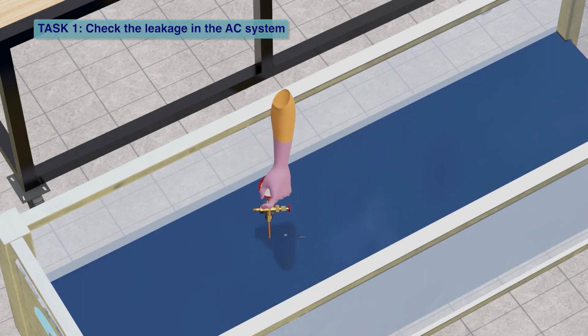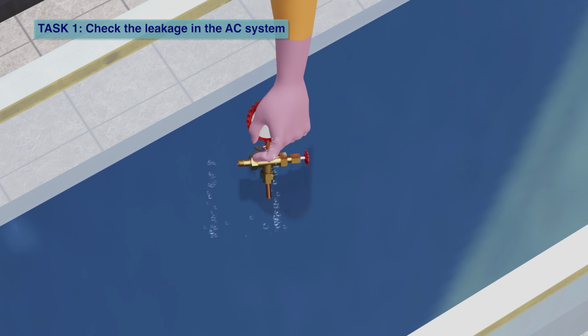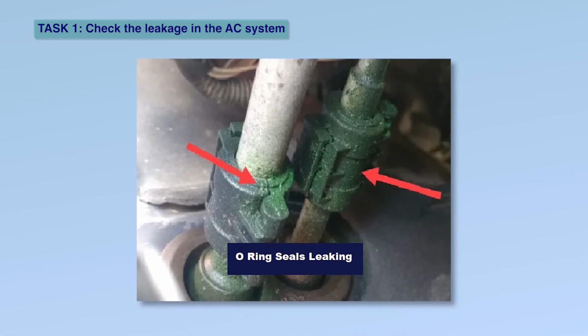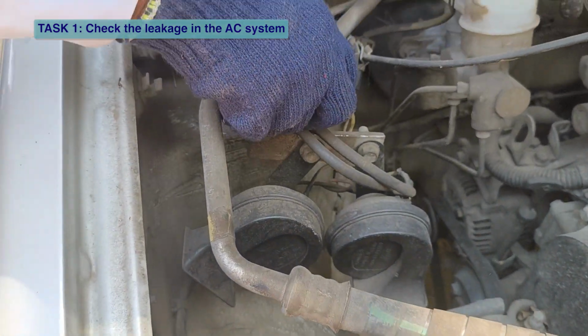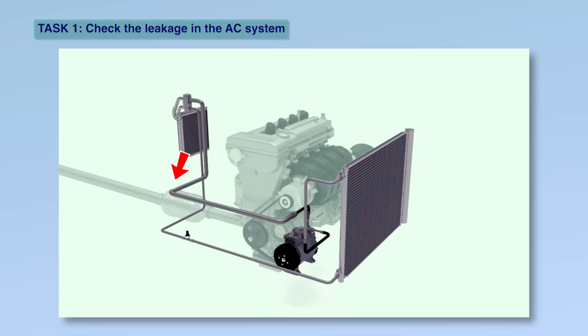Check the evaporator for leaks, particularly inside the cabin around the drain pan area. Look for worn or cracked O-rings and seals at hose connections, compressor and evaporator. Ensure the hoses and fittings are not cracked or loose and are properly tightened. Inspect for frost or ice accumulation on the AC lines indicating low refrigerant level or leak.